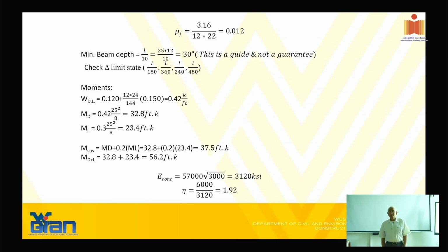That component gets very difficult computationally when you deal with pre-stressed concrete beam design. I mean, that is an approximate number, but if you deal with a pre-stressed concrete design, due to the pre-tensioned loads and what have you, you have to make a combination of live load, dead load, and the pre-stress loads. That is where they use the factor. That's what we use. I don't know what you use in India. 1/3 is our number for creep.